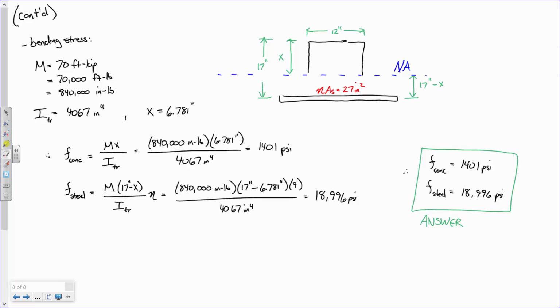What's the significance of the cracking moment? That's a good question. I'll give you two quick answers. The first significance is that the cracking moment is what we will use later in order to determine what's called an effective moment of inertia. And that's what we use for deflections. The idea is that some of the beam is cracked, some isn't, so you use sort of a weighted average approach. The second reason is, especially in pre-stressed, the cracking moment and the cracking stress is used for serviceability limits. But for us, we'll use this later in deflection world. So that would be my best answer.